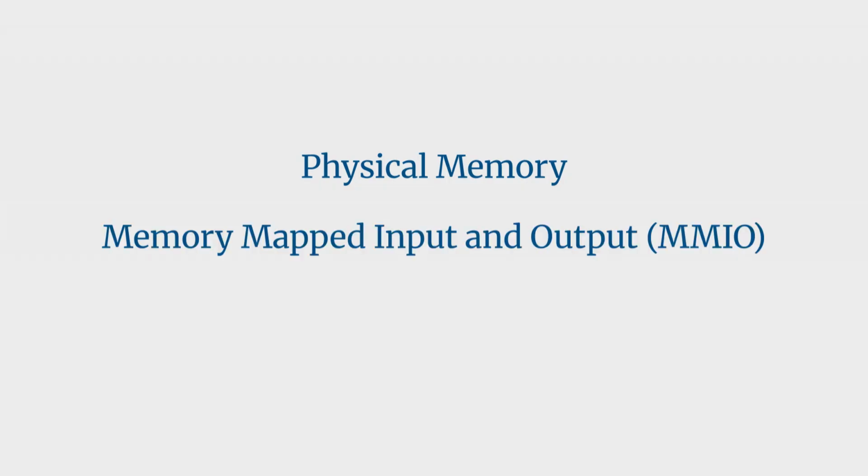We're also going to talk about what happens when your CPU tries communicating with hardware that doesn't exist, or you don't have proper permissions to access. If you have prior experience with virtual memory, page faults, and segmentation faults, this last topic will be similar to that, but will be operating at the level of the physical address space instead of the virtual address space.